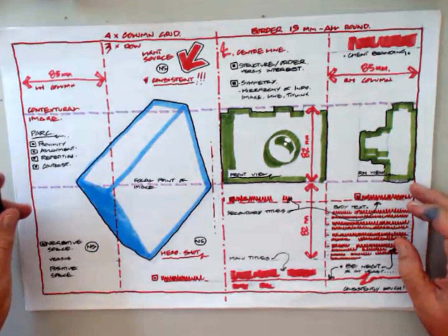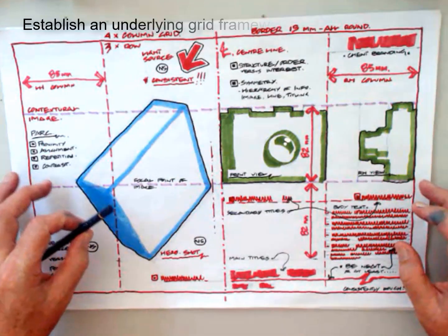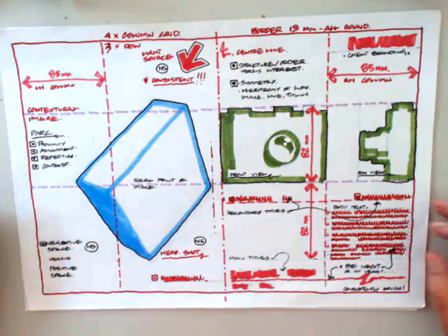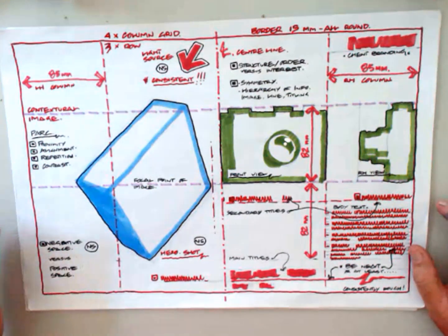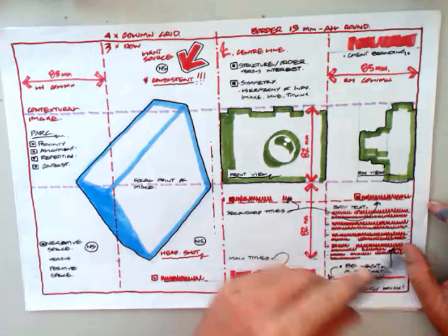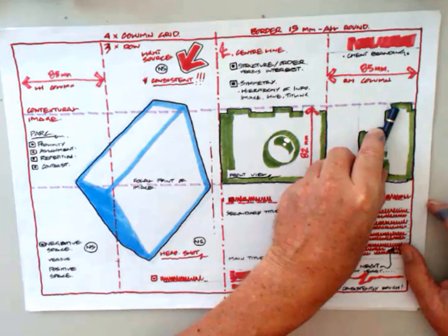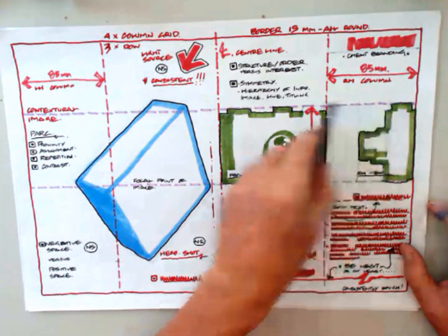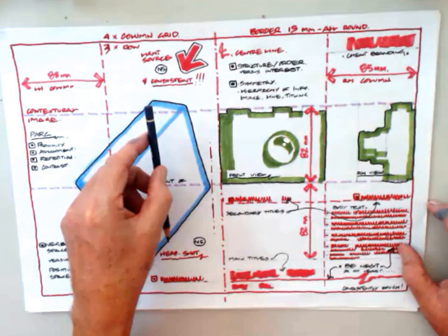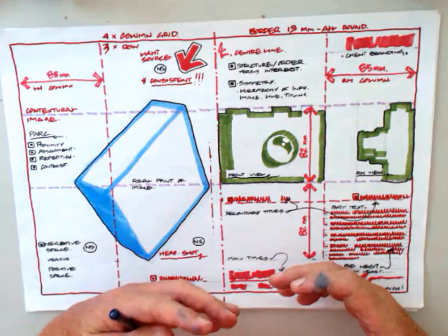The next thing is having a grid structure that you can use on one sheet or multiple sheets, such that there's a consistent framework or skeleton that you can build your presentations off. So in this particular case, I've gone for a 4-column grid, and it's an asymmetrical grid in so much as I've got 2 equal columns on either side of 85 millimeters, and in the center I have a center line, so the 2 remaining columns are that residual space. So they're not consistent columns, but you can play around with these and experiment yourself.